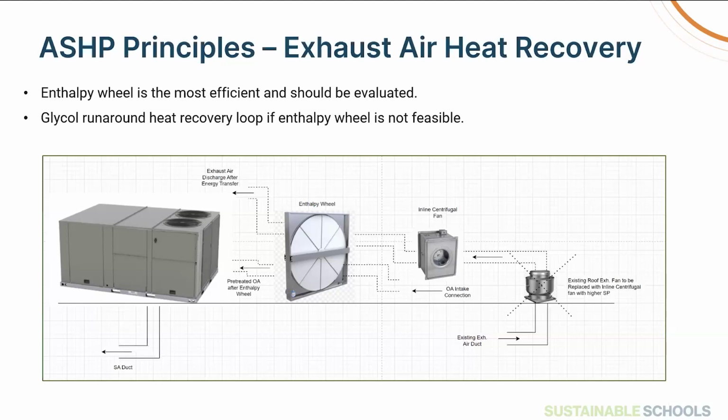But even though the payback of the addition of exhaust air heat recovery may or may not look attractive at this stage, that heat on the coldest days when the air source heat pump's no longer giving you heat will be invaluable. So we're big believers that if you can get the enthalpy wheel installed, and you can ask your suppliers and your consultants for premium costs, which with rooftop unit applications you mostly can.